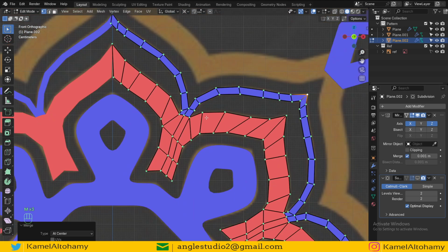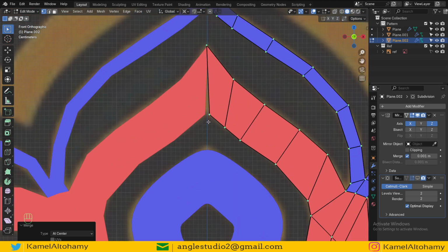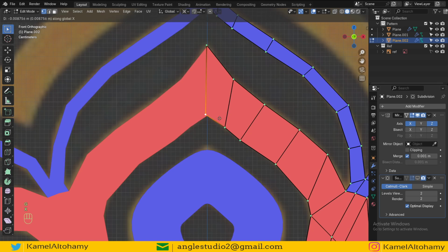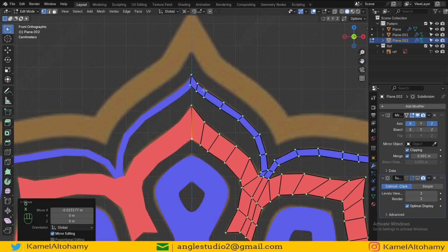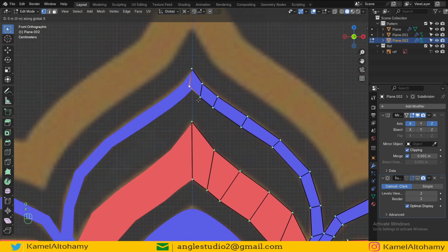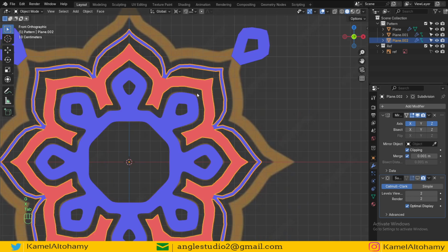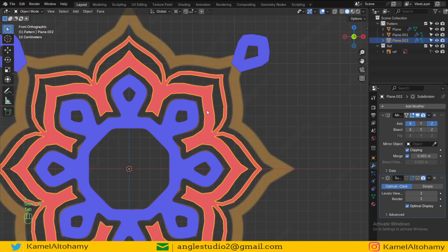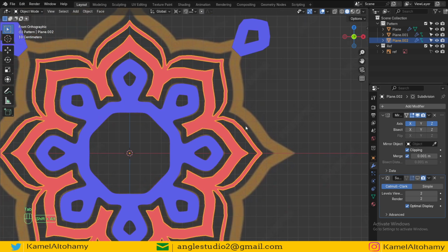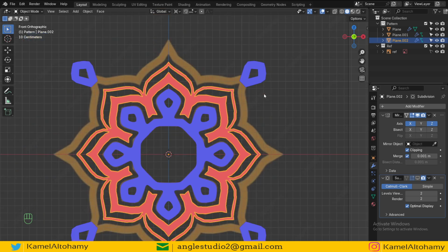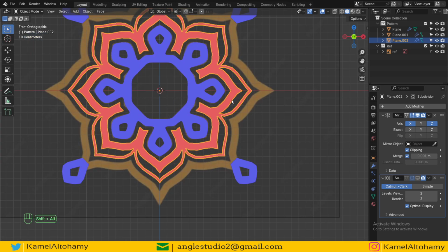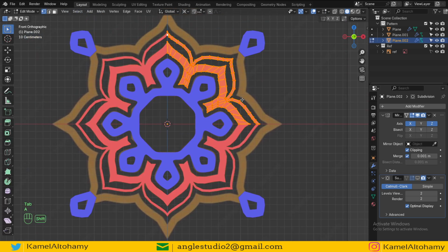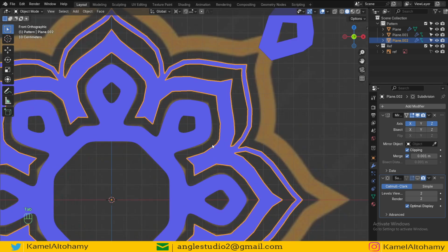We have an old video explaining that in the channel, but it's based on Blender 2.8 or 2.7, so I recorded that, and in the next few days I will publish a few lessons to explain how we can make 3D logos. The same thing here, we will press Shift N to recalculate these normals, and that's fine.